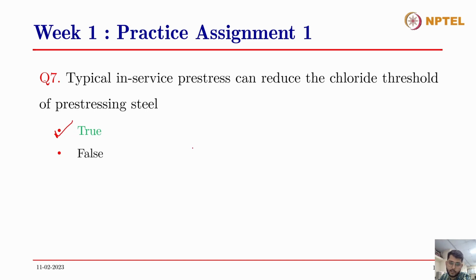Additionally, inducing stress to the steel will also affect the surface of the steel by producing certain deformities or irregularities on the steel surface, which will again promote the corrosion process by creating cathodic and anodic reactions on the steel surface.